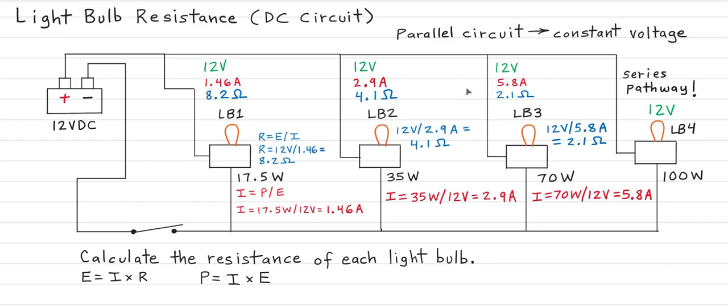So when we combine all these circuits, we're actually going to multiply a certain amperes times the resistance to get then the voltage here. So this is like the answer, but we don't know the root of that answer. So what we can do is just go ahead and solve for current as we would usually solve for current. 100 watts divided into 12 volts, 8.33 amps.